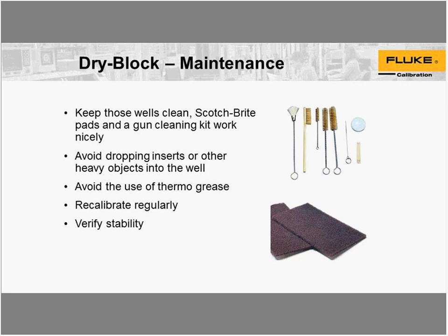Drywells, we're going to touch on the maintenance now. They have metal blocks. Typically, they're some sort of brass or aluminum block material. For units that have these types of blocks or inserts, metals oxidize. Even if you're not using extreme temperatures, even on the cold ones, you will get some condensation out of the air, like on your kitchen sink, where you get these small micro buildups.